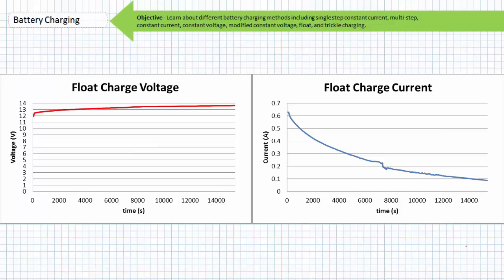In this case, the charger is set to float at 13.8 volts. However, sensing that the battery is initially deeply discharged, the charger limits the applied voltage to keep current below a recommended limit, in this case around 0.3 C20. As cell voltage rises, the voltage differential between the charger and the battery erodes, and the current decreases. Over time, the float charger progressively steps up the float voltage to 13.8 volts.